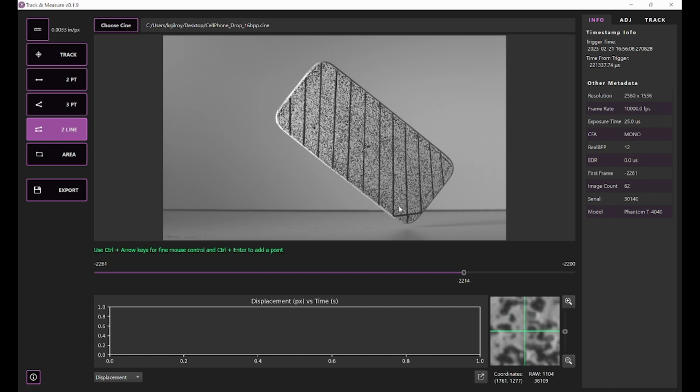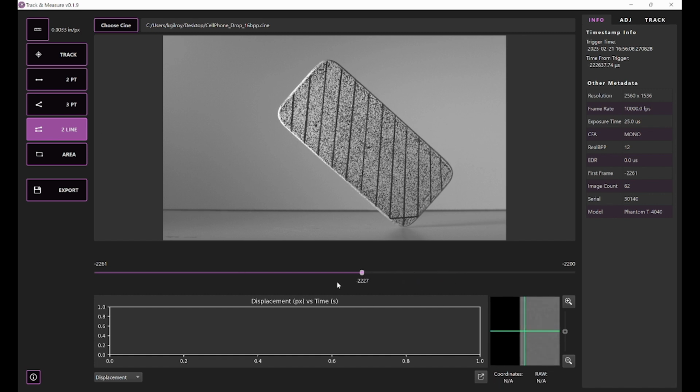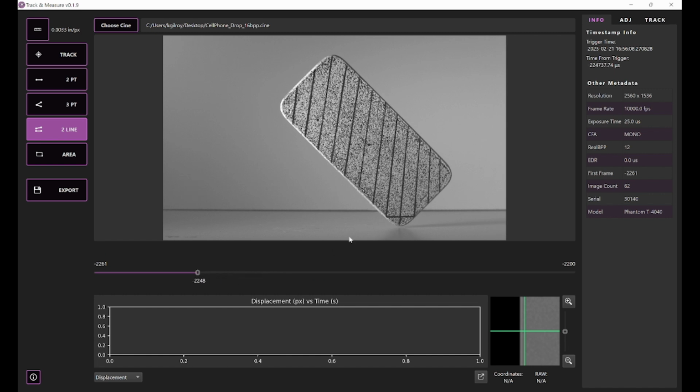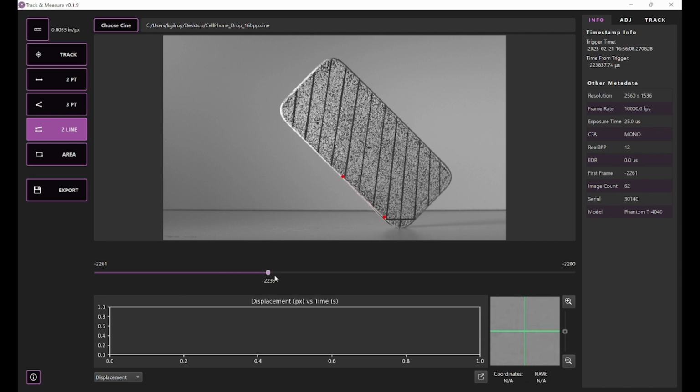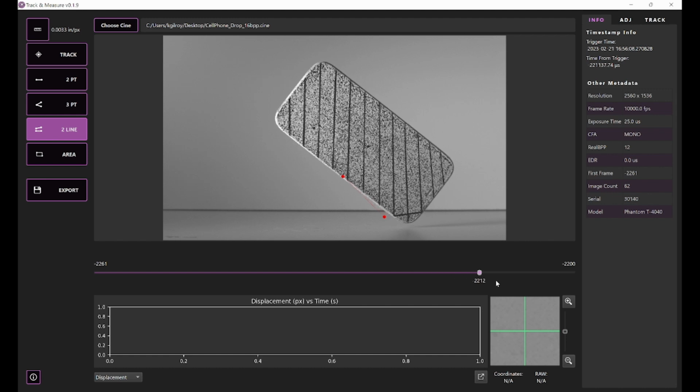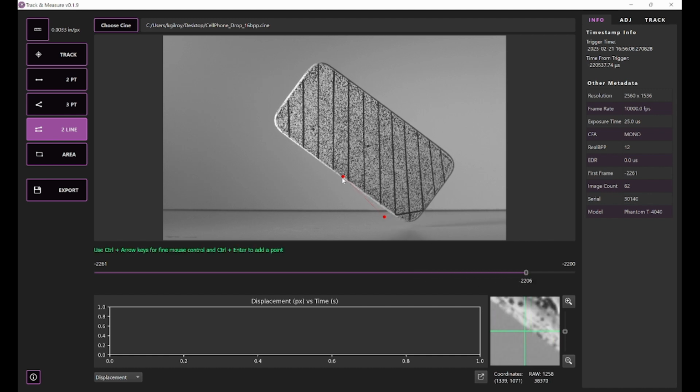Okay, here what we can do is draw a line along the edge that is constantly falling here. Then we can progress it in time to a moment of interest, for example, in the future here, and get approximately the rotational rate along the edge. So we can see that the angle between these two lines is around 8 degrees. And we can see directly after impact, this thing is rotating at an average rotational rate of around 1900 degrees per second. And I progressed 42 frames to observe that drop.